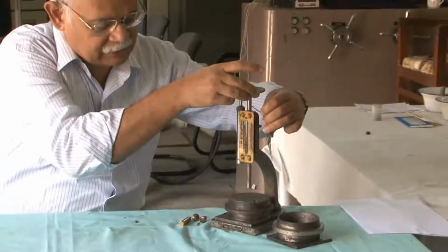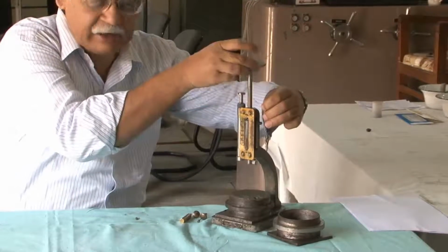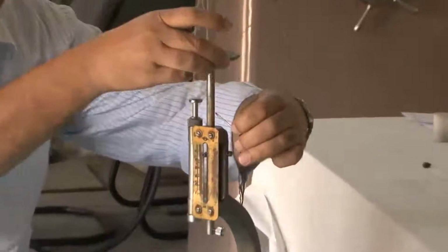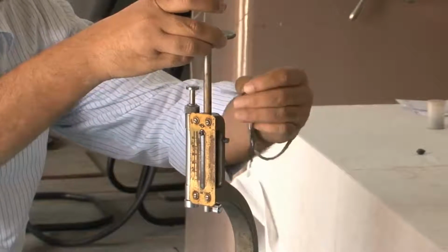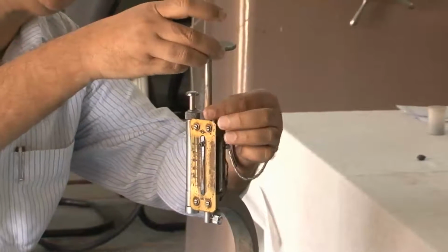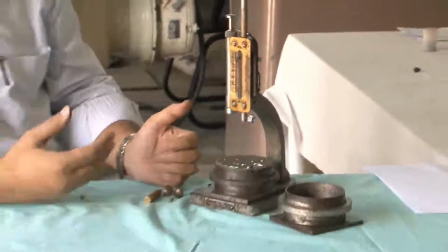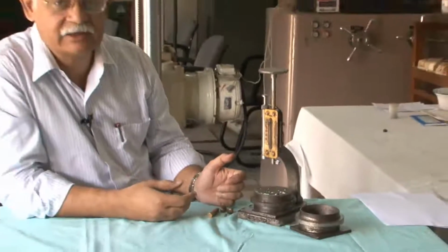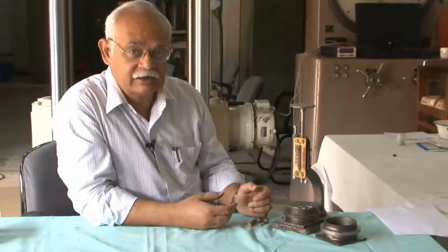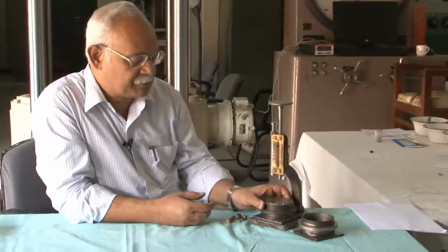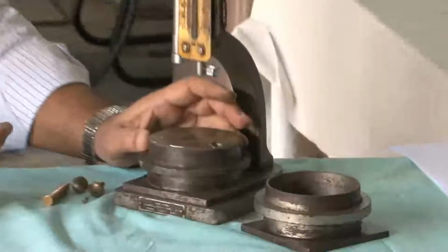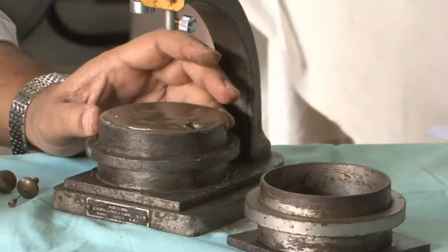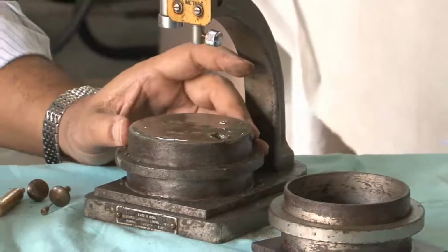mechanism by which the plunger or the needle is allowed to fall into the cement paste, and depending on the kind of penetration resistance that we get, we have our observations in terms of the consistency, standard consistency, initial and the final setting time of cement, determined using a paste sample which is here, which is placed in this mold and is nothing but a mixture of water and cement.